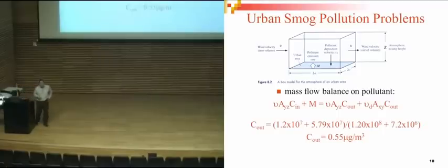Okay, so very similar to the problems we solved before. Steady state, conservative pollutant, so we can set the mass in equal to the mass out. The only thing that's a little different here is you have to make sure you understand how we set up the control volume and that we are given a mass emission rate and a lead deposition rate. So those are, again, in and out of the system.